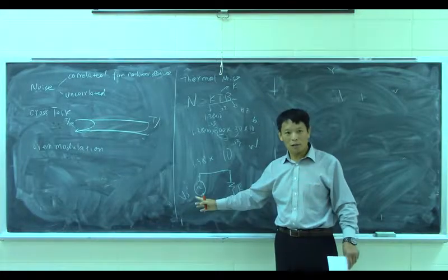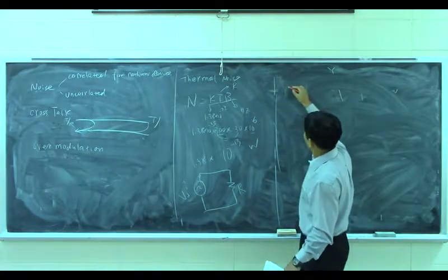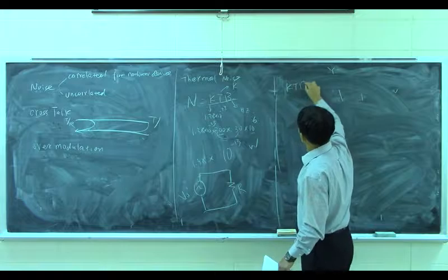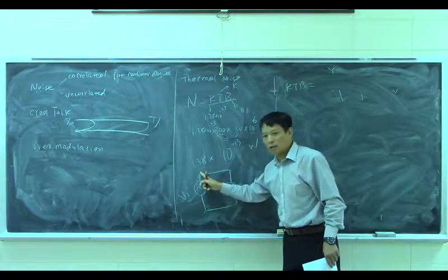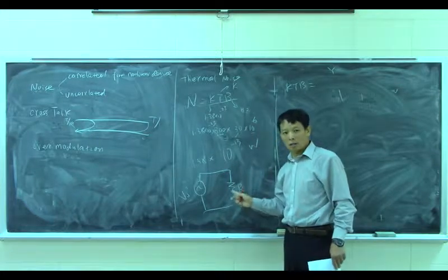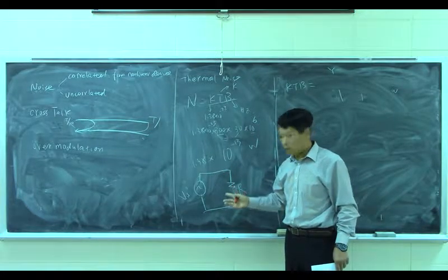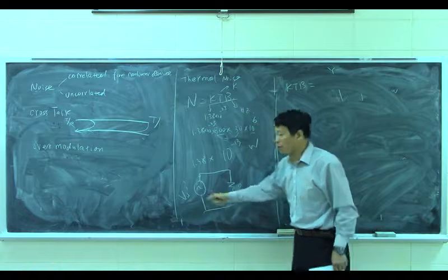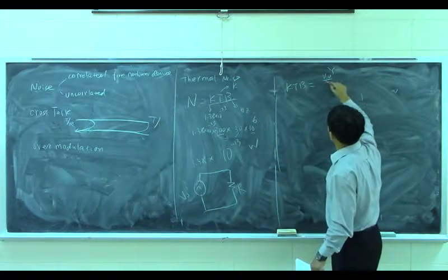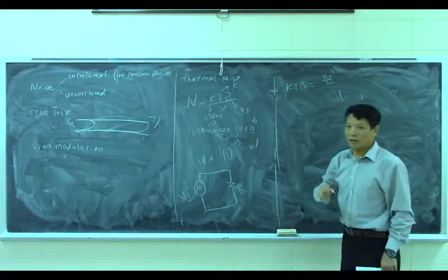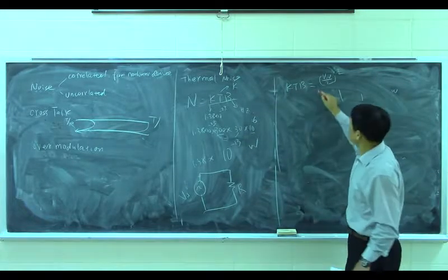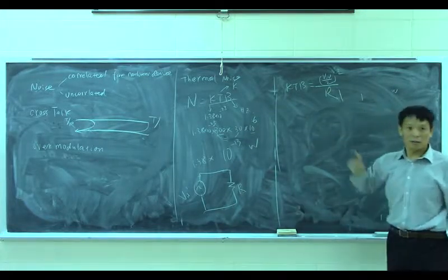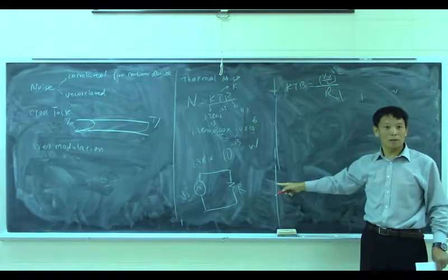Based on this rule, the power kTB, because when this equals this one it gets the maximum power, so that is the worst case. So this voltage will be equal to half of this Vn. So Vn over 2 is the voltage over here. Then V squared divided by R gives us the power on this.